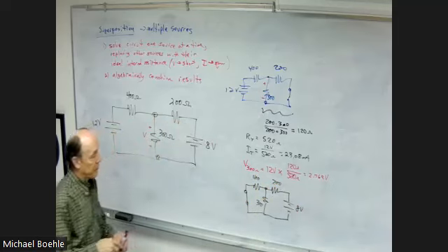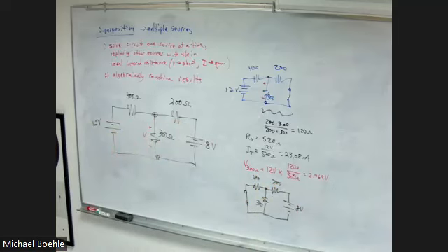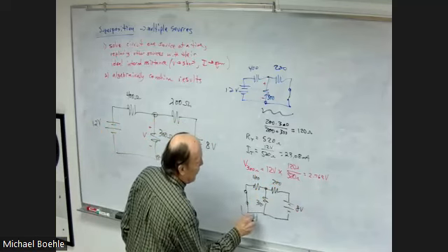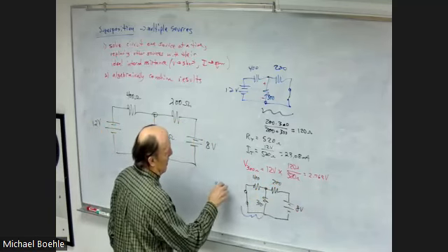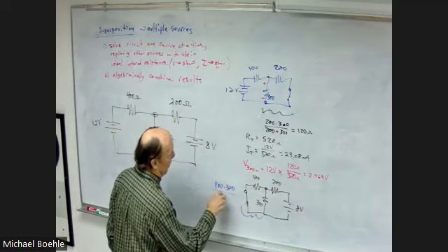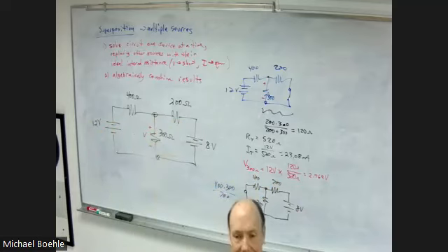All right. So now, again, I have 2 resistors in parallel, different resistors this time. So 400 in parallel with 300. Product over the sum. I'll just add it in my mind there. I can do that sometimes. So that gives me a resistance of 171.4 ohms.